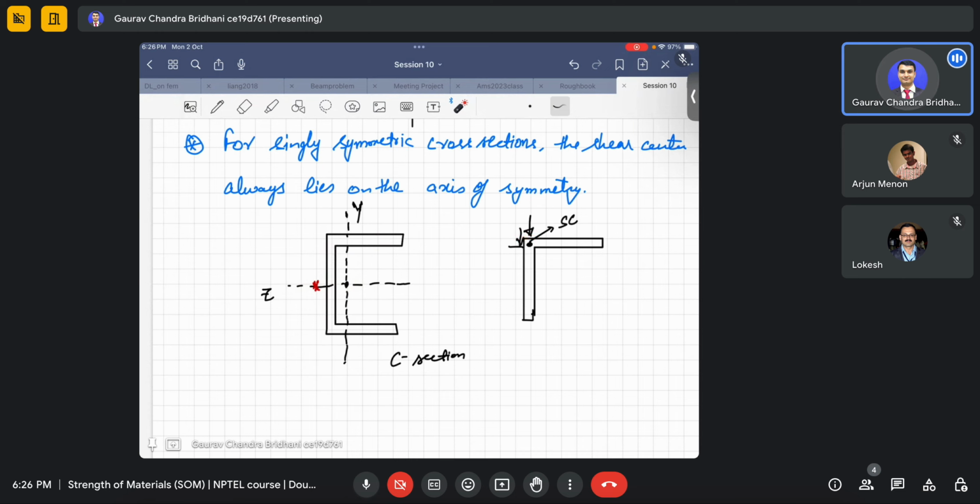So instead of that, he put a protrusion here, and on that protrusion he put the load. So it was very near to the shear center, and that's why we couldn't see any rotation. However, when he put it along the centroid, you could see the cross section rotating. In the same manner, if you load the channel section in this way here, you will see the channel rotating.